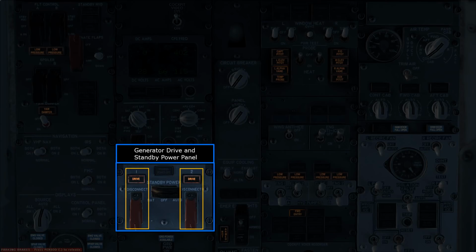So in this aircraft, electrical power is usually supplied by electrical generators built into the engines. So when the engines are running, they spin a generator and produce electricity for the aircraft. If there's a problem with one of these generators, this light will come on. When the engines are switched off, it's normal for these lights to be on, because the engines are not running, therefore the engine generators are also not running.